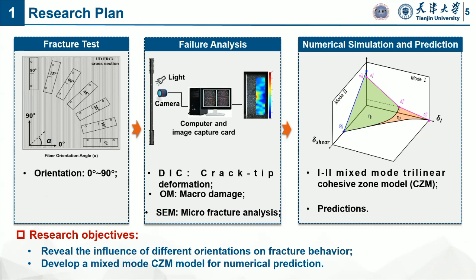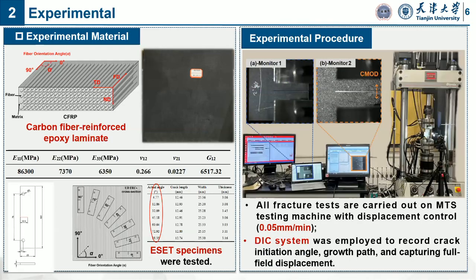The third part uses numerical simulation and prediction. We developed a mode 1 and mode 2 mixed mode trilinear cohesive zone model and predicted the tensile curve.